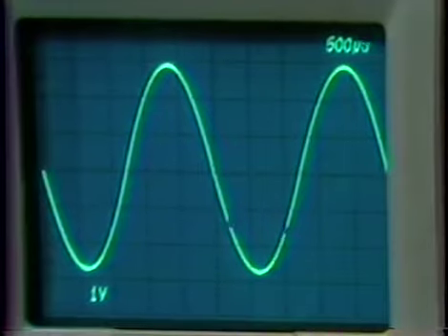That says that we would get into the nonlinearity at an input signal level of 6 volts divided by 80, something under 100 millivolts. Our amplitude scale here is a volt per division, so we're getting nearly 3 volts peak at the input. Clearly, we're driving the nonlinear element through its linear region on a very small fraction of the signal applied to it.